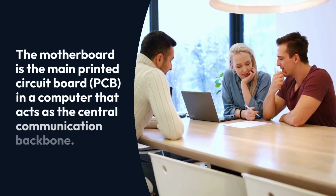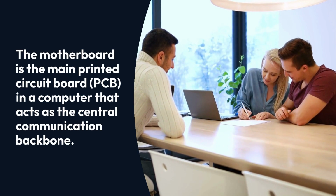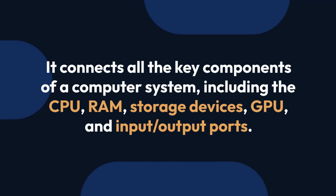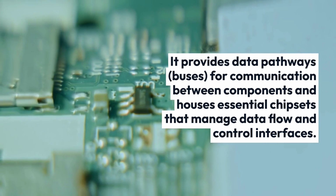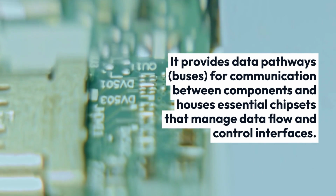3. What is the function of a motherboard in a computer system? The motherboard is the main printed circuit board, PCB, in a computer that acts as the central communication backbone. It connects all the key components of a computer system, including the CPU, RAM, storage devices, GPU, and input-output ports. It provides data pathways, buses, for communication between components and houses essential chipsets that manage data flow and control interfaces.